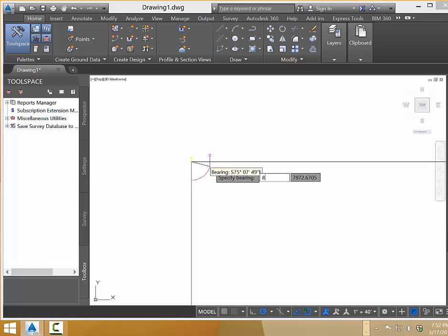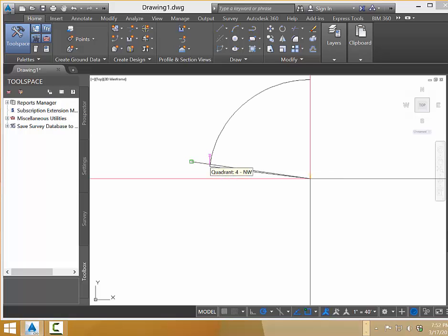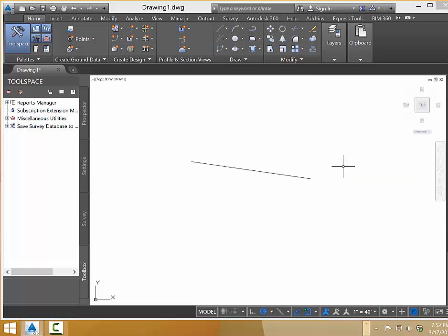So I'm going to say 81.4215, for 81 degrees 42 minutes 15 seconds. And I hit enter, and you can see it's snapped to that angle. Now it wants to know a distance, so I'm going to say 971.26 feet, I assume. And now I've got that bearing set. Okay, I might move it down a little bit instead of panning the screen.